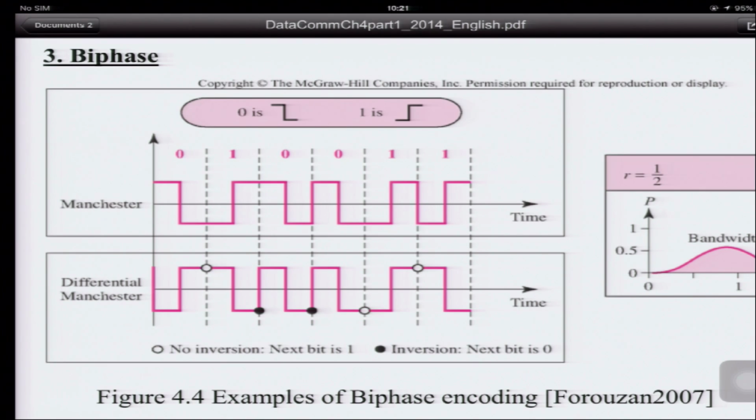However, you can see that the baud rate is very high, because you change very quickly. Inside of one bit, you must change at least once. So it changes much more frequently than the NRZ or than the AMI. And therefore, you need more bandwidth in this case.